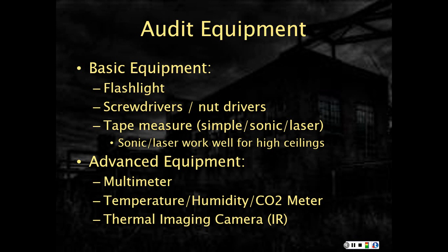A temperature, humidity, CO2 meter of some type is handy. CO2 is good to decide if ventilation intake is adequate. Temperature and humidity also important, so we know if they're within the proper tolerances for the type of space that we have. And then finally, thermal imaging camera.